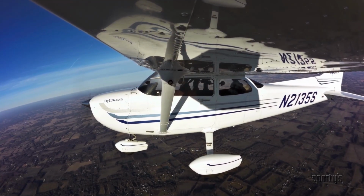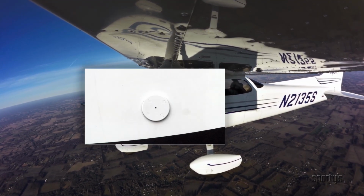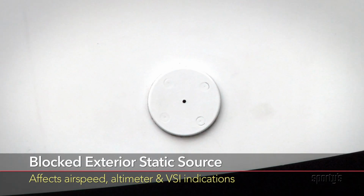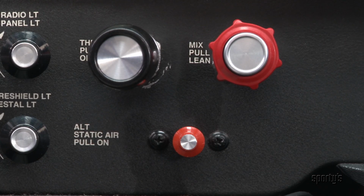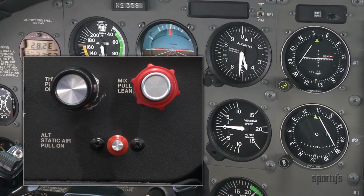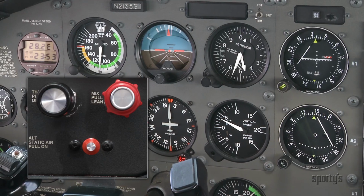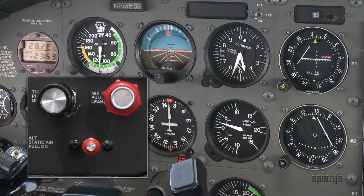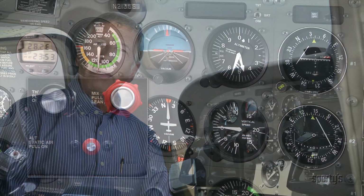Also worthy of a mention is the alternate static source. If the exterior static source becomes blocked, the pitot-static system can be returned to operation by selecting the alternate static source. This vents the system into the cabin. Some instrument indications will be affected by this change, so talk to your instructor about your specific trainer.